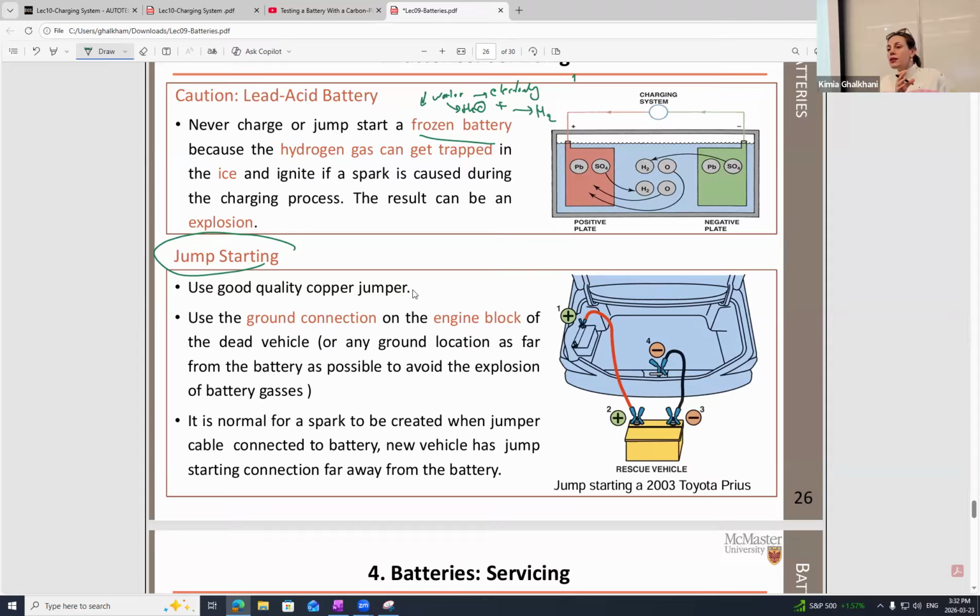And remember, I had some valve. If you recall from the previous session, if not, go watch those recordings. Inside the battery, especially lead acid, remember I said we do have a built-in valve in order to get rid of the excess hydrogen and avoid explosion of the battery. Remember that. Now, water is frozen, hydrogen is around. That simply means if I start the vehicle, that hydrogen is in a situation where it can immediately cause an explosion.